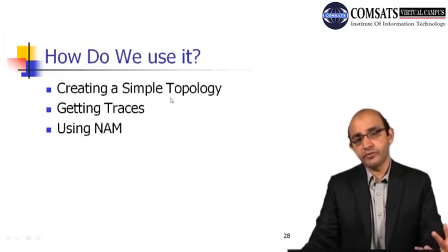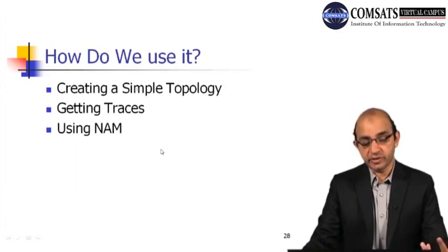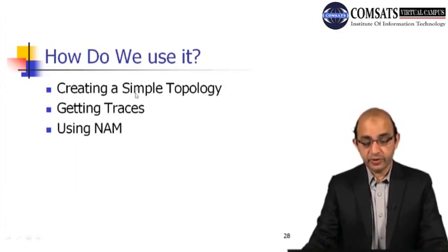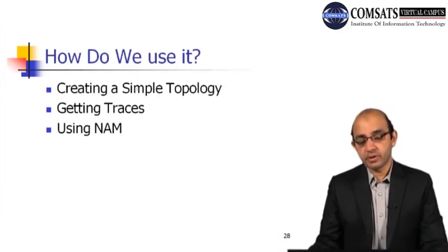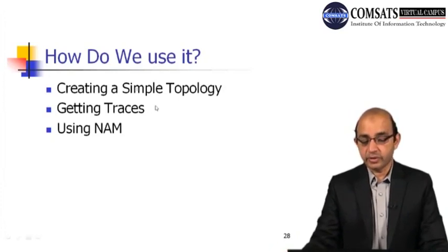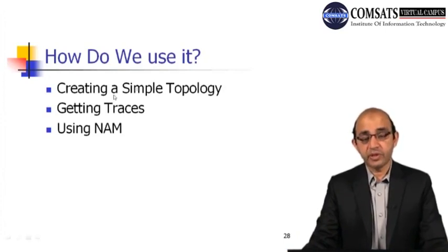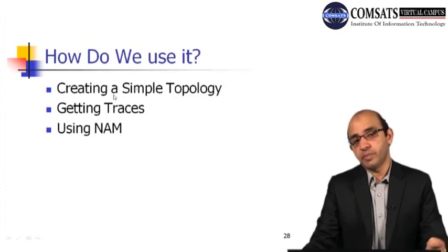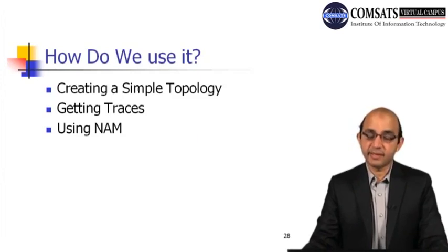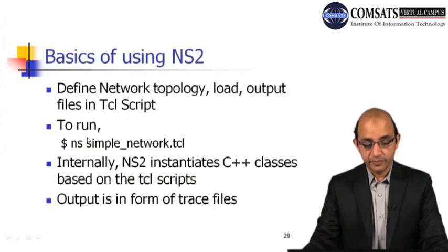So first of all, how are we actually going to generate a simulation scenario? First, we will think about the topology, so how the components and different cables are interconnected. Then, after generating the topology, we will put in the tools, connect them, and decide on the protocol, the bandwidth between different links, the delay, the packet size, and so on. After that we will get traces, right?